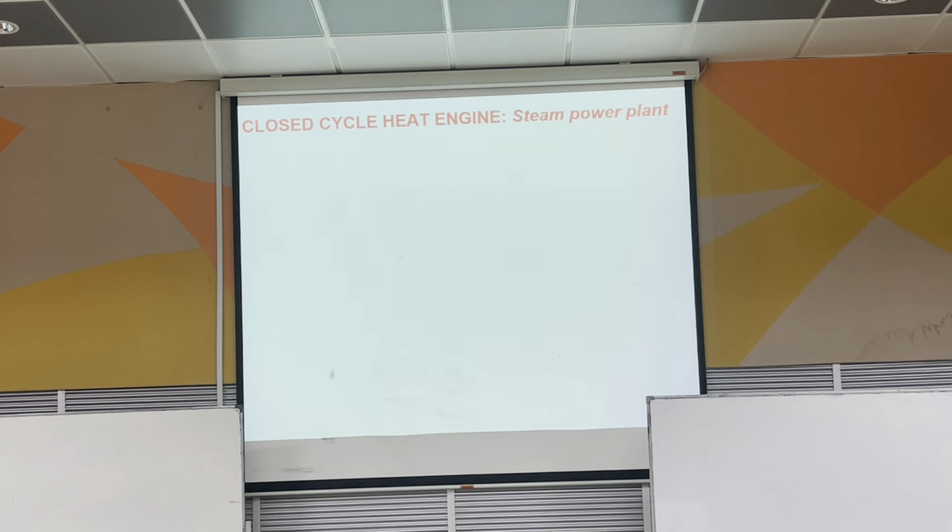But in general, again, like I said, I cannot remember whether I give you the second form of this equation. But in general, this is a very easy to derive equation. So I don't recommend you memorizing anything. Just keep to this one. If you can remember this one, then you can solve this whole thing. Meaning, if you can remember work net is Q in minus Q out, then just use the normal thermal efficiency equation.